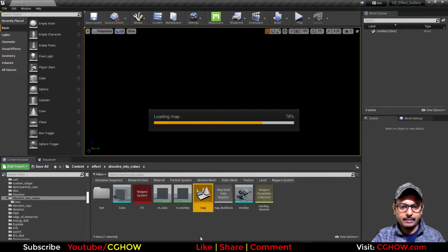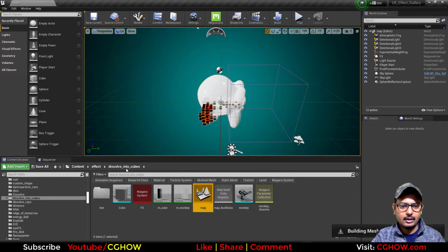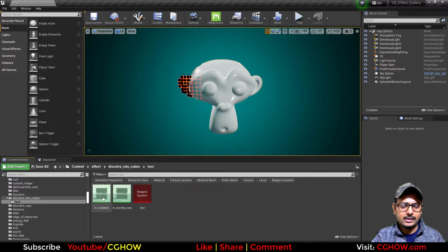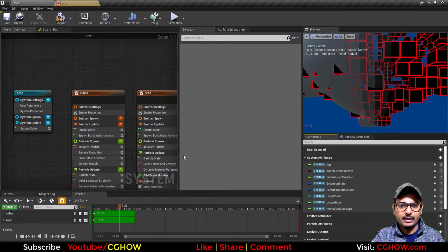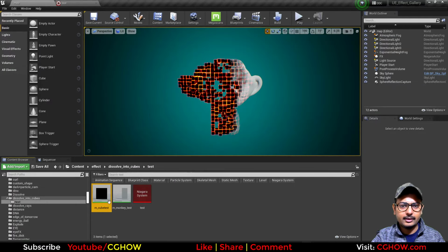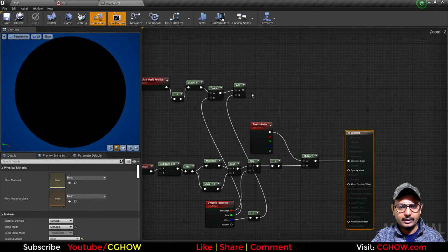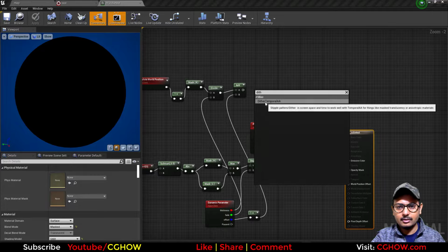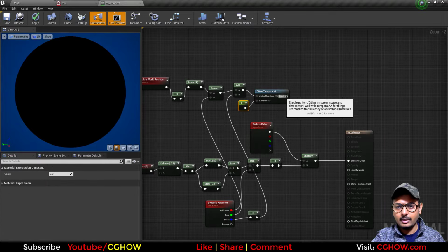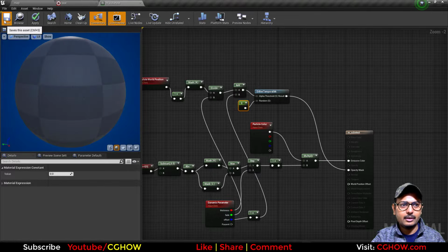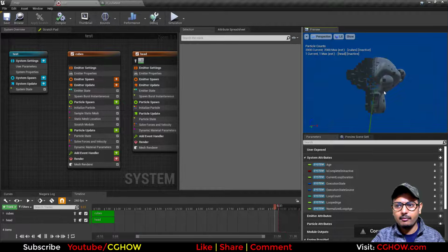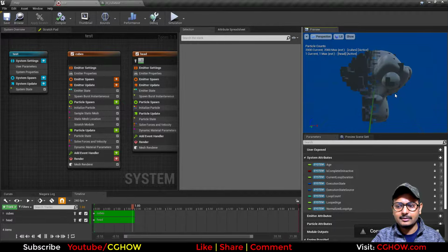Let's just open that map again and press G, and now the test folder and the test for FX. So what we were doing, we were doing in materials. So in cubes we need here dither, and the value I will use is 0, and then connect it to opacity mask. Save this, and now in the FX you will see we have already done our basic thing.